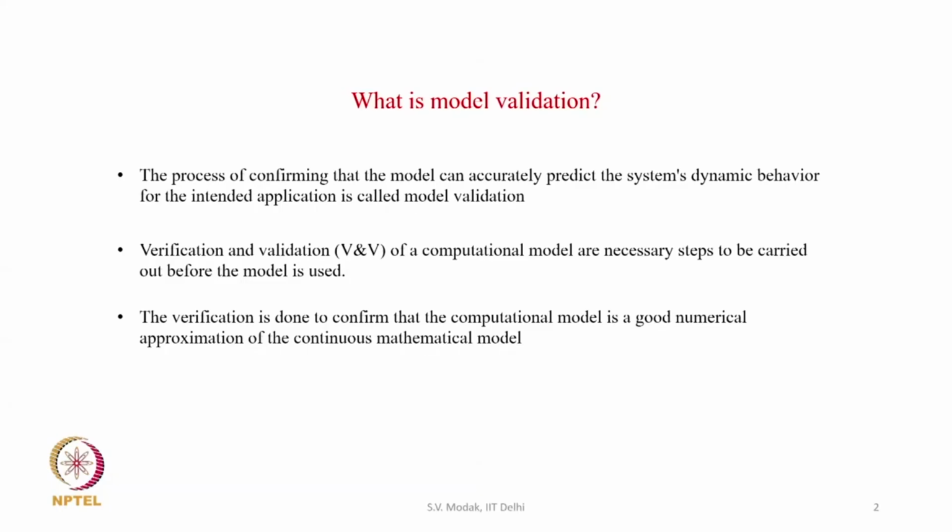So the verification is done to confirm that the computational model is a good numerical approximation of the continuous mathematical model. So generally we use discrete models to analyze a system. For example, a finite element model or some other numerical model is a discrete representation of the continuous system, right. So in the model verification, it is checked whether the discretization error associated with the discrete model is negligible. So we would like to ensure that the discretization error is small. Verification also involves checking the validity and correctness of the codes and algorithms that are used to ensure that they are error free. So verification is the first step of checking the model.